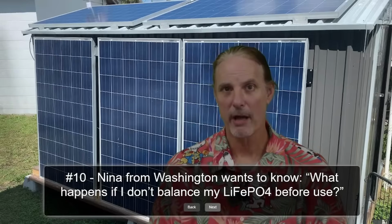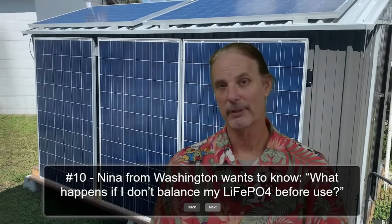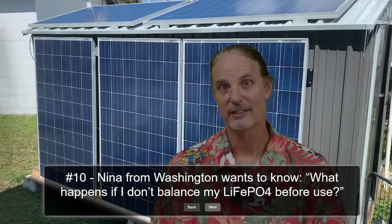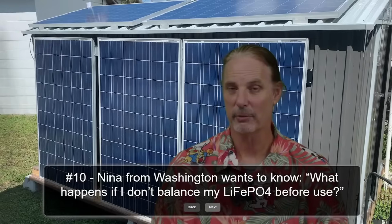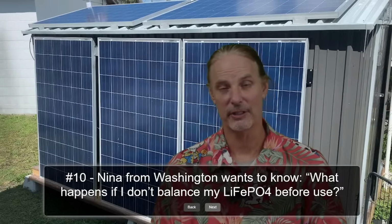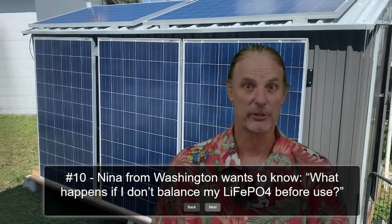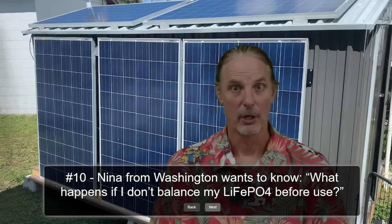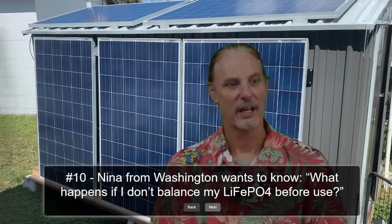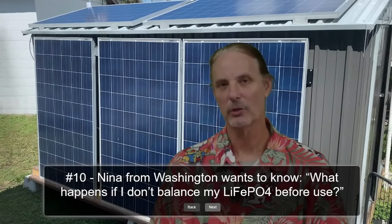If you're talking about a battery that you build yourself, like a DIY battery, then that would be a completely different scenario. It could be anywhere from it shuts off early until such time that the active balancer can get in and move things around, and that could take a while depending on how big your cells are and how big your balancer is. Is it an active balancer that's moving 5 amps at a time? Is it a passive balancer that's burning off a tenth of an amp at a time? Depending on those cases, it's going to depend on what would happen. Most likely, if it's a store-bought battery in today's world, nothing.